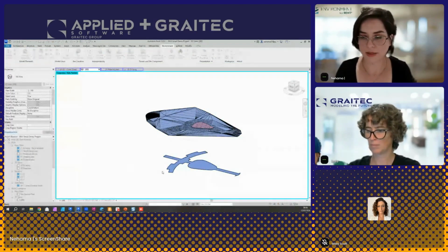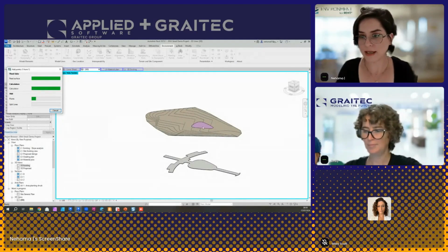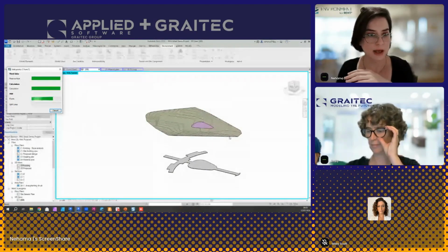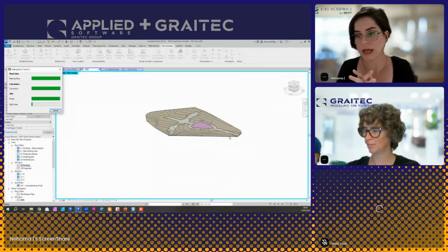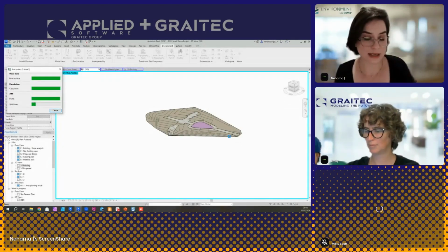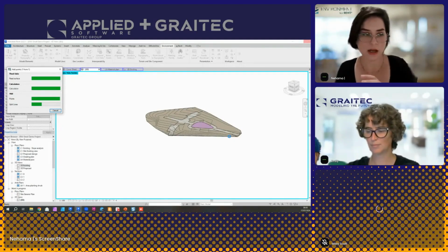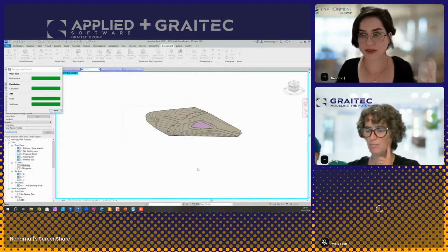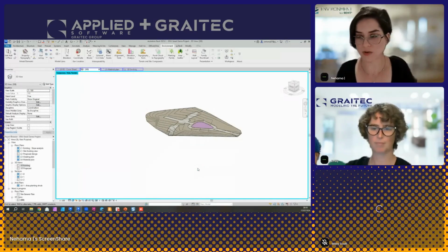And that's essentially the reference surface. So again, the advantage of that is that every other part that I add to my design could just be aligned with the same topo surface, the same reference surface. So essentially, I can have as many reference surfaces like that as I want in my file. But you just have to think about what bunch of paths or roadways have the same grading logic, so that I could just align them to the same surface.